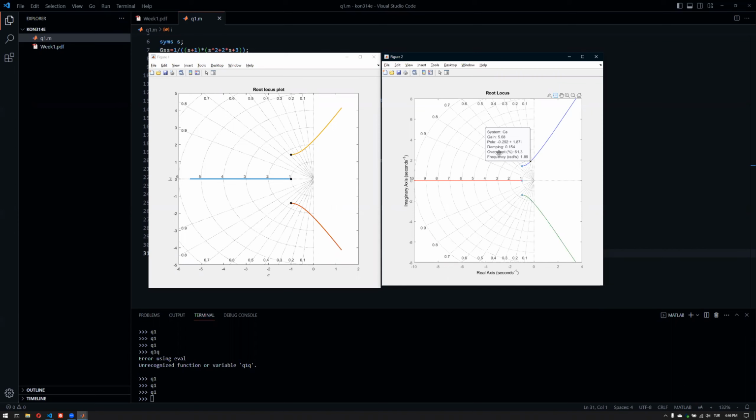So if you read something like overshoot is 61.3%, then what this graphic or Root-locus tool tries to tell you is that if the system consists only of this pole pair, then you would get this damping ratio, overshoot, and frequency. It doesn't belong to the whole system, because I can also click this branch here, and it will give us a totally different overshoot and totally different time domain data here. And it doesn't actually correspond to the system's overshoot.